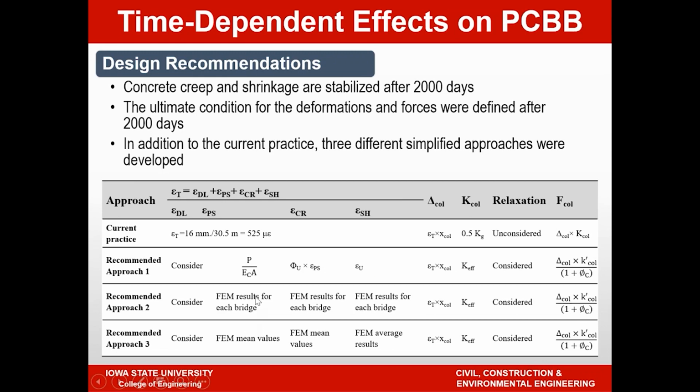The second approach, we basically use the finite element results that we calculate for each and every bridge, but use a simplified analysis to determine the base shear forces, the top level displacement and the base shear forces. So you would expect this approach to be more accurate because each and every bridge was modeled based on what we learned from the analysis of finite element.